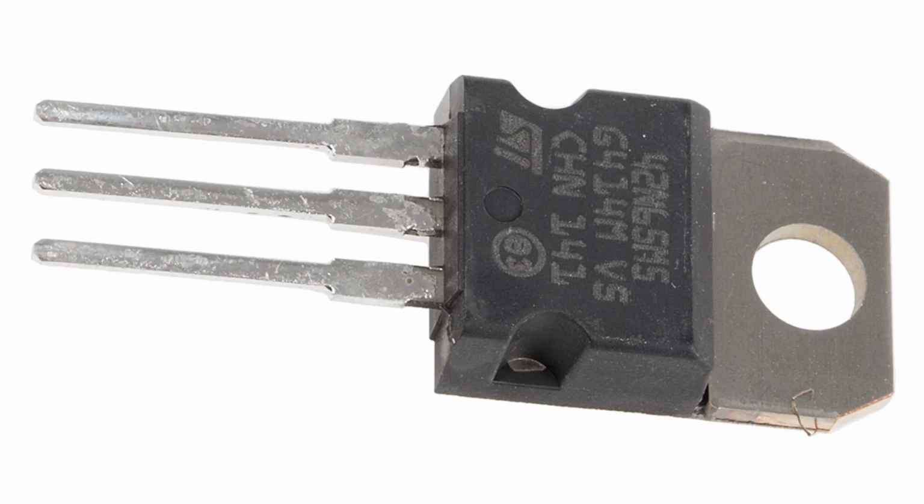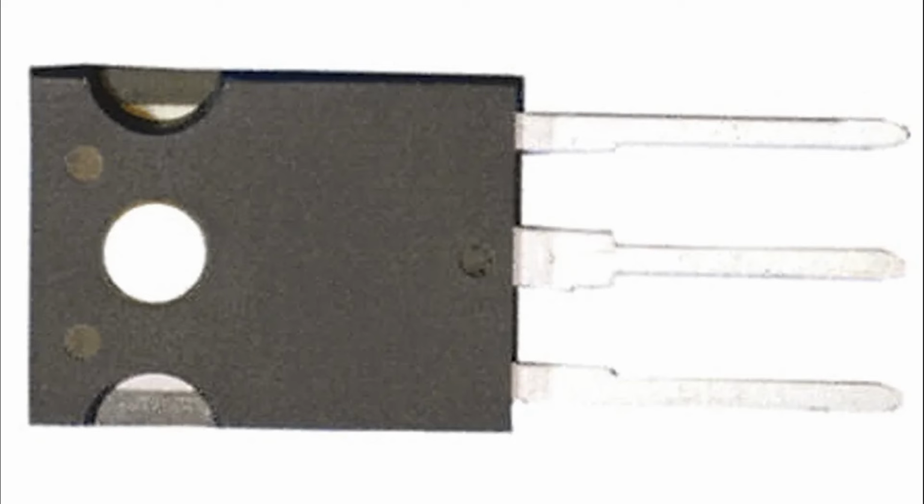3. High input impedance. Description: The insulated gate design results in a very high input impedance. Advantage: This characteristic allows for lower gate drive current requirements, leading to reduced power consumption and simpler control circuits. 4. Low thermal resistance. Description: Power MOSFETs are designed to dissipate heat effectively. Advantage: This property allows them to operate at higher power levels without overheating, increasing reliability and longevity in demanding applications.